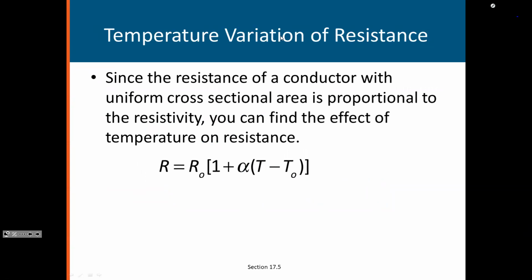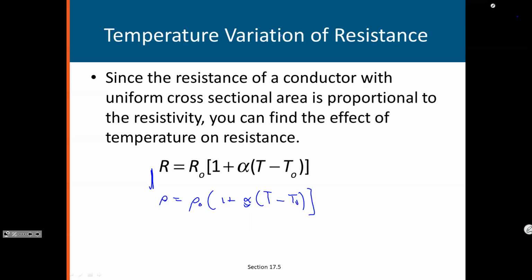Okay, right now we can also write an equation for resistance. What we had before was resistivity, which is proportional to the temperature, with the proportionality constant called the temperature coefficient of resistivity. But we know that these two are related to each other, and provided we have a uniform cross-section, we can say for a given piece of resistor, its resistance is also proportional to the temperature.